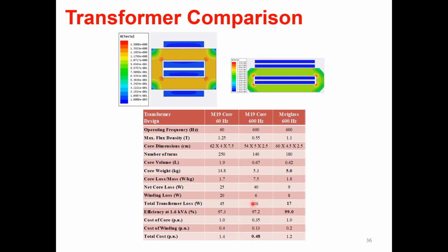But of course, with a slightly lower efficiency. But if you go to an amorphous silicon core, you may still be able to balance the cost of the conventional line frequency transformers at higher efficiency. So these are certain things to keep in mind.